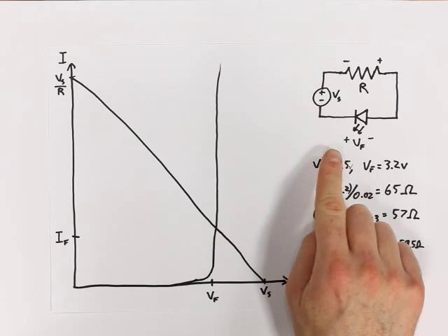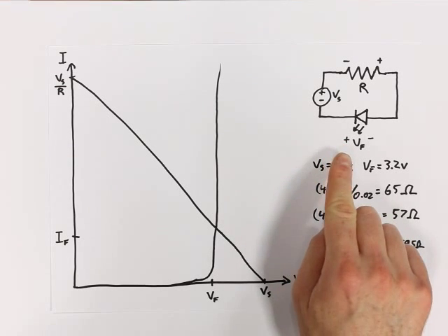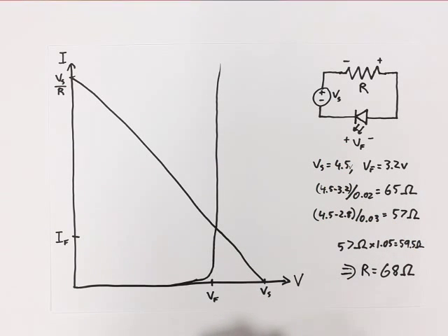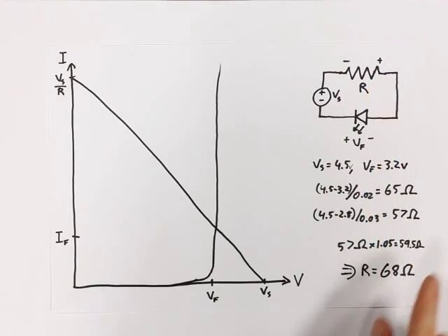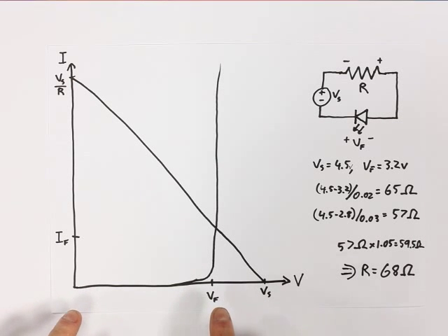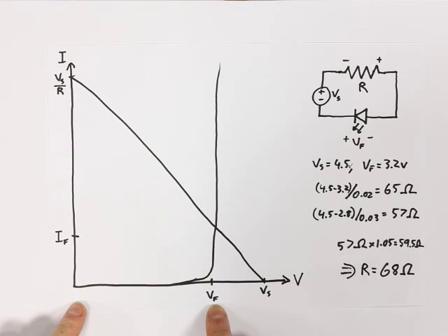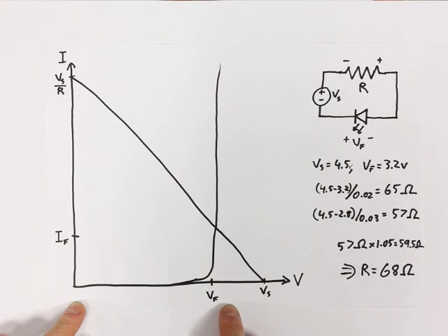Now, to summarise what we've done, we initially looked at a series resistor circuit. The advantage of this circuit was that it was incredibly simple, but there were significant power losses through the resistor. And the efficiency of this circuit was pretty much proportional to the ratio of the forward voltage of our LED to the supply voltage. So we could have chosen a supply voltage which was closer to the forward voltage of the LED in order to improve efficiency.